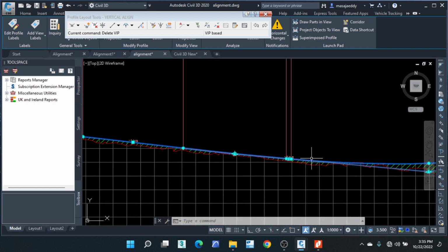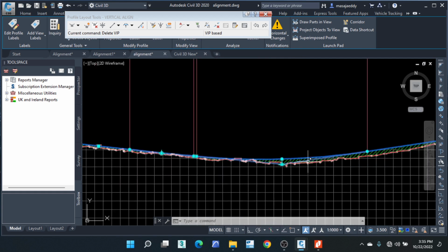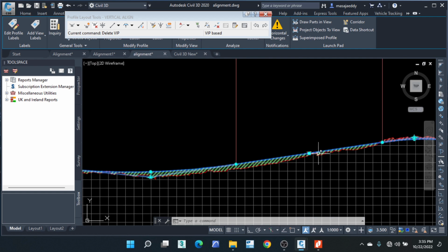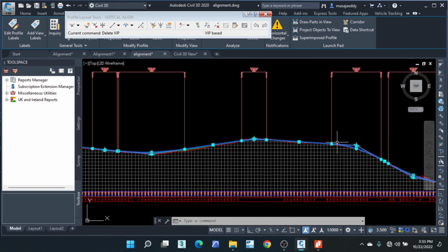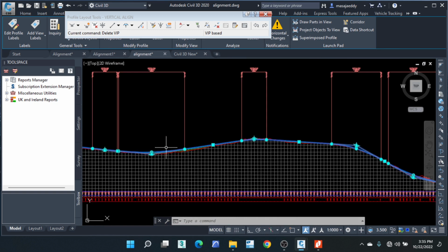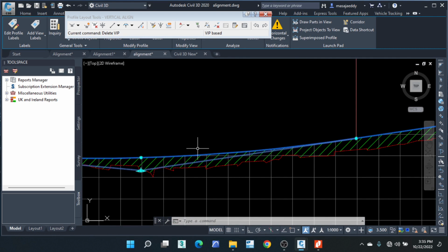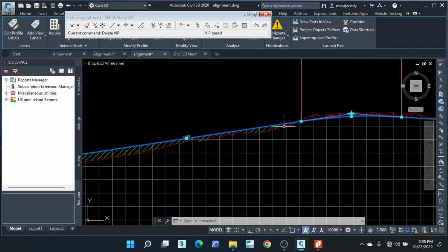Then make sure the curves don't touch. Your minimum slope is more than 0.5%, whether negative or positive, because the lowest is 0.5. That is for drainage. So always I try to create a smooth curve, not with many PIs as well. Where we have percentages, you keep adjusting until you get your percentage more than 0.5, and it adjusts automatically.